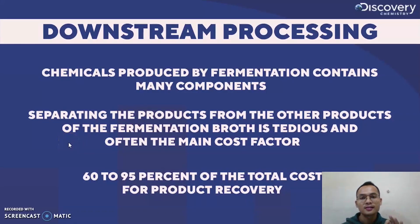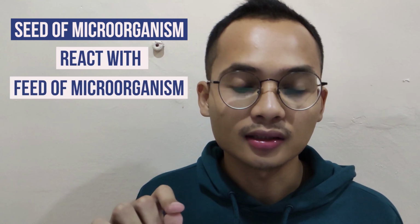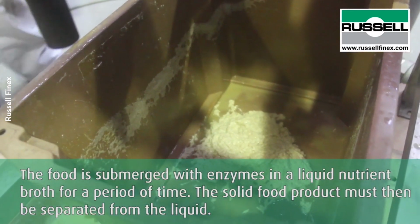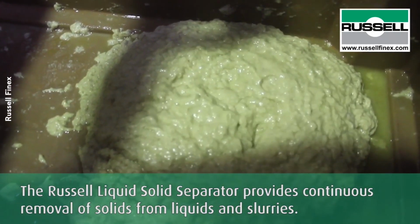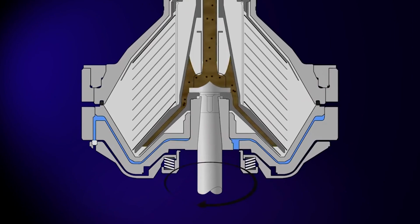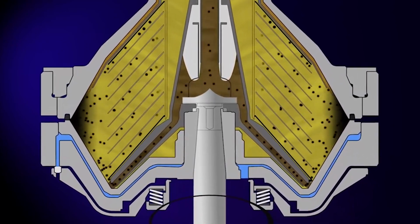The last part is downstream processing. As I mentioned earlier, after the seed of the microorganism and the feed of the microorganism are reacted in the fermenter, it will produce a fermentation broth. The fermentation broth, or the chemicals produced by the fermentation, contains many components such as water, undesired strains, and bacteria. So the downstream process is needed to separate the products from the other components of the fermentation broth, and it is tedious and often the main cost factor.